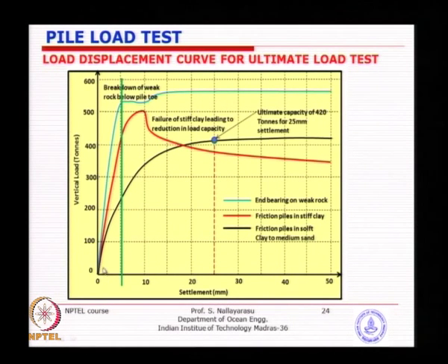If you look at it, this is completely elastic, and after that only becomes the plateau. So you can see the difference. So that's the way we want to determine when you do a testing. I want to determine what is the ultimate capacity. The thing is, you have to firm up what is the displacement at which you would like to take.